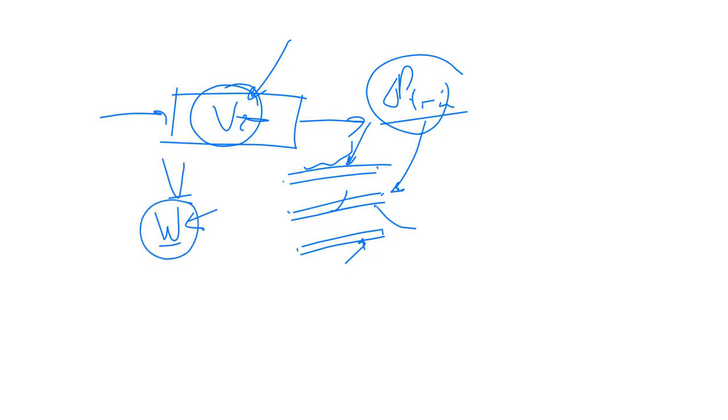So the first part is to say, right, this is the amount of catalyst, this is the volume, and then fine-tune. Design is always an iterative process. So you will first get just a mass, and then you will say, all right, how am I going to distribute it in tubes? Is it going to be in a CSTR? Of course, you're going to decide on your type of reactor first, CSTR, PBR, PFR, and then you can finally start your design process.